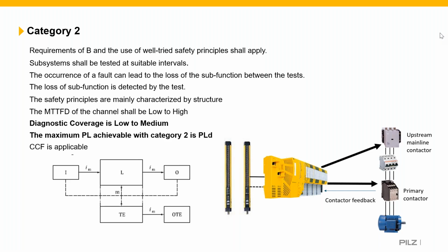And we've modeled this architecture with a light curtain in the graphic, because as many of you may know, when you're doing stop performance tests for electrosensitive protective equipment, or light curtains, you'll do your 13855 calculation of S equals K times T plus C, with T1 and T2 being the values which make up your overall reaction time and mechanical stopping time of the safe control system.